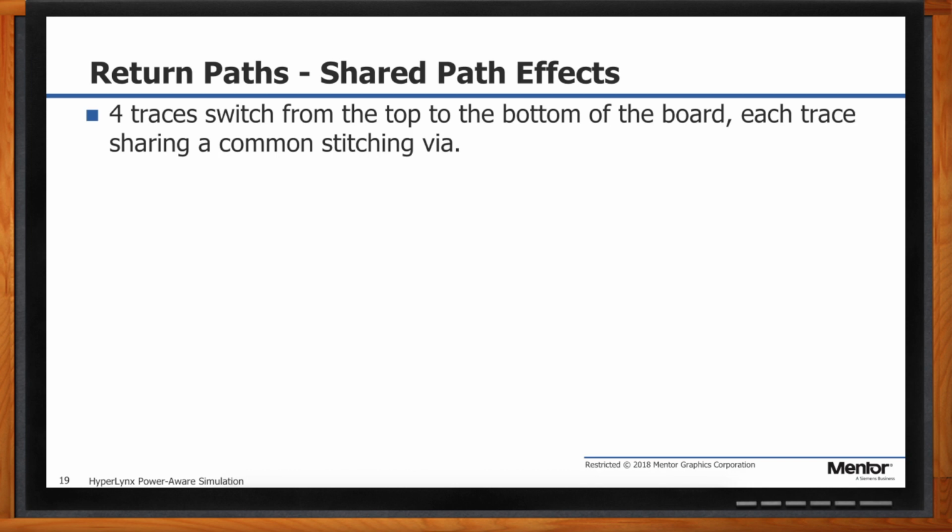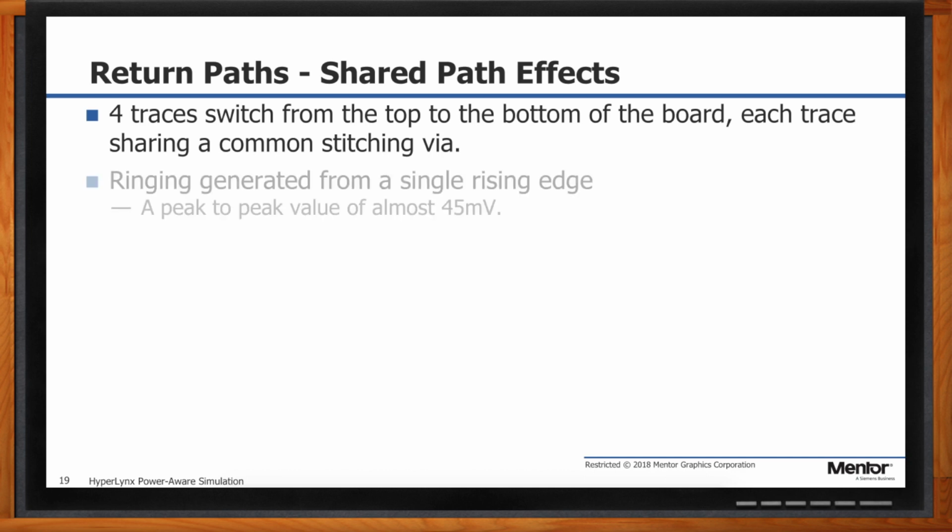One is getting power to parts. The other is providing the reference for the signals as they propagate from chip to chip. We never want to put enough ground pins on our components because we'd rather use that space for signals or something else. So we're always trying to figure out whether we can get away with a few fewer ground pins so we can use that space for something else.